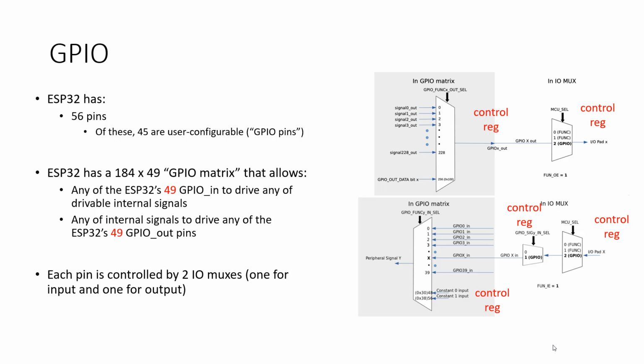So there's 45 of these multiplexers that allow you to connect internal signals that can be used for output and send them to the pin as output. Now, likewise, there's also the reverse situation for inputs, right? So there's an output mux and an input mux for every pin, because I think just about most of the pins can be used for input or output. You guys with me? Now in this case, we're only doing output, so don't worry about the bottom part. We're only worrying about output.